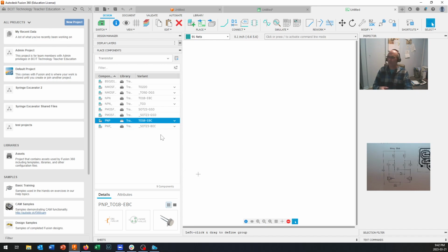You can have a through-hole part, a surface mount part, a 5-watt resistor, a 10-watt resistor, or a 20, okay, well, massive resistors, as well as our little quarter-watt resistors, all represented by the same resistor symbol. So finding both the part that you want and the footprint can sometimes be a little bit challenging.